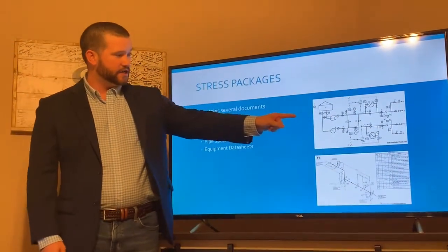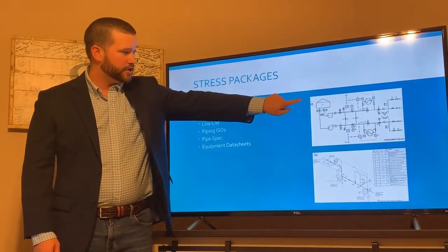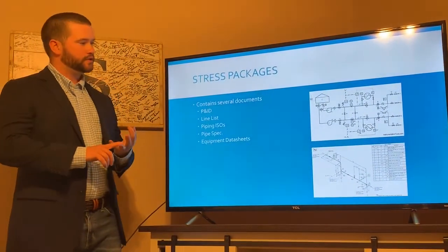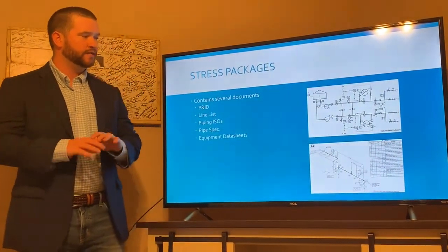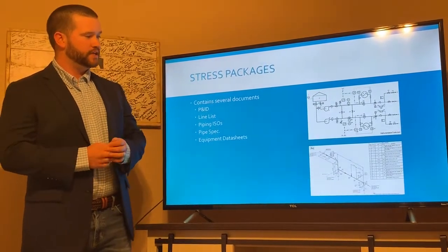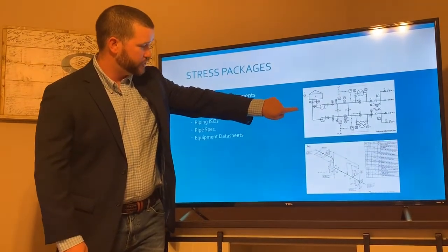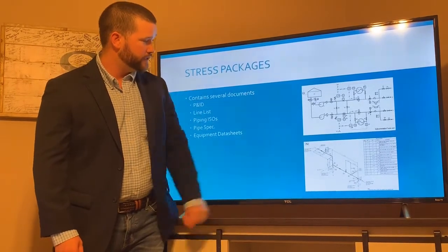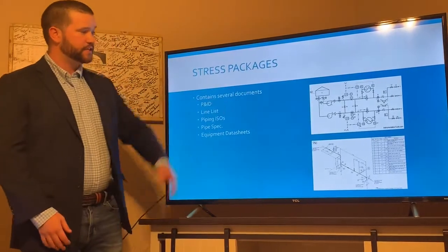And a P&ID is a document that has all of the equipment, the valves, the pressure vessels. This here, a tank. So you have equipment, vessels, valves. You have electrical lines and signals running in there, but none of it has any dimensions. It's just basically a flow diagram of what equipment should be contained within this system. That way, if you see coming off of this tank, there should be two lines with a valve each, and then a jump over with a valve in between them. If you look at your ISOs, your isometric drawings, then you should see that equipment on there.